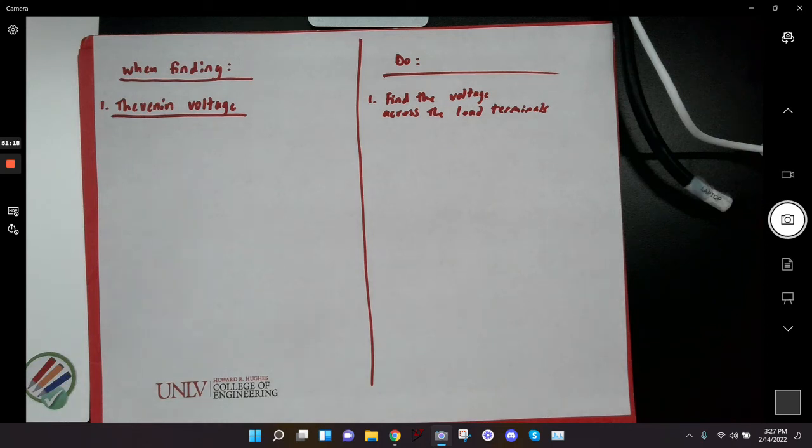Because if it's a voltage source, I short. Is it a current source I'm removing? If it's a current source, I open. Right. And if it's a resistor, then yes, you open. If that's what you're asking.